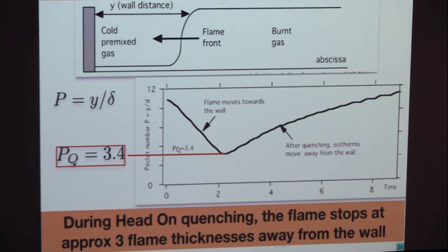You cannot go closer. Which really means that the fuel which is left here is not burning. It's going to do something. Usually it diffuses into the burned gases. But in a piston engine, for example, you have crevices where the fuel can basically hide, because you have walls on all sides, and get out when the exhaust valves are open. And that's a process for pollutant generation.